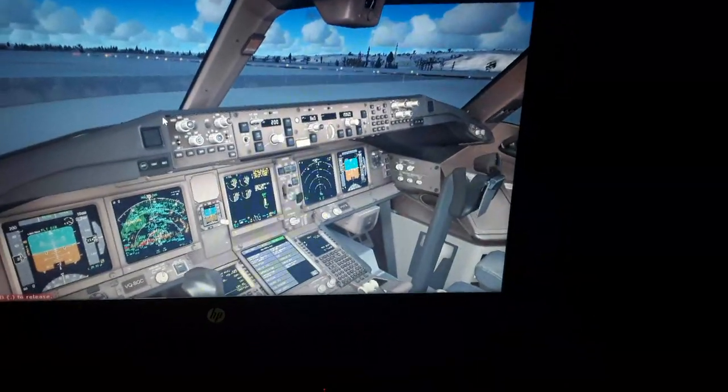So we're going to make these calculations, and then we're going to input the SIDs, the standard instrument departures from the runway. We're going to select on the airport the intermediate waypoints and features and the destination airport and runway with the STARs, the standard terminal arrival routes and waypoints, and the LSZH localizer for the destination runway. So we're going to make a complete route for the later vertical navigation profile of the aircraft. We're going to fly manually or using the autopilot and flight director system panel and the auto thrust. So I'm going to show you how to do that.